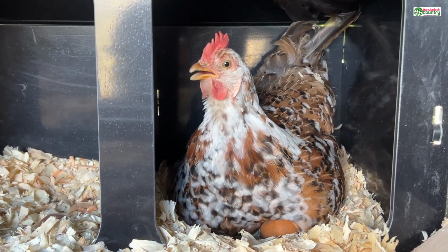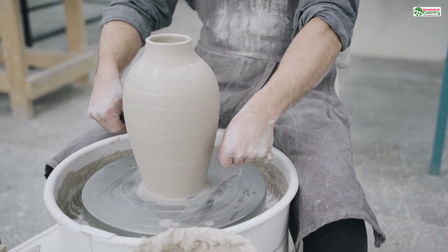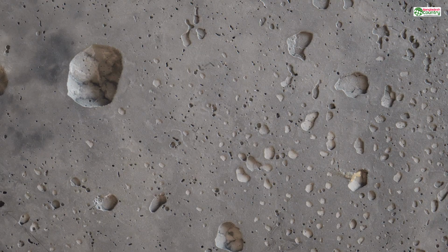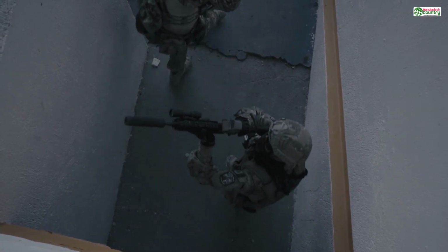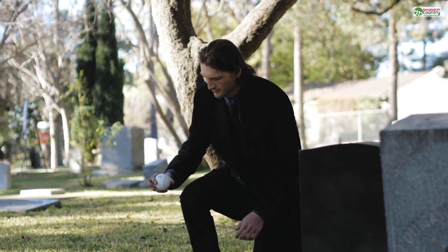Hollowing dramatically reduces that cross-sectional area. Instead of a solid disc, you're just printing a thin ring. The suction forces drop to almost nothing. The internal stresses disappear. The print survives. So hollowing isn't just a cost-saving trick. It's a professional technique for ensuring quality and success.